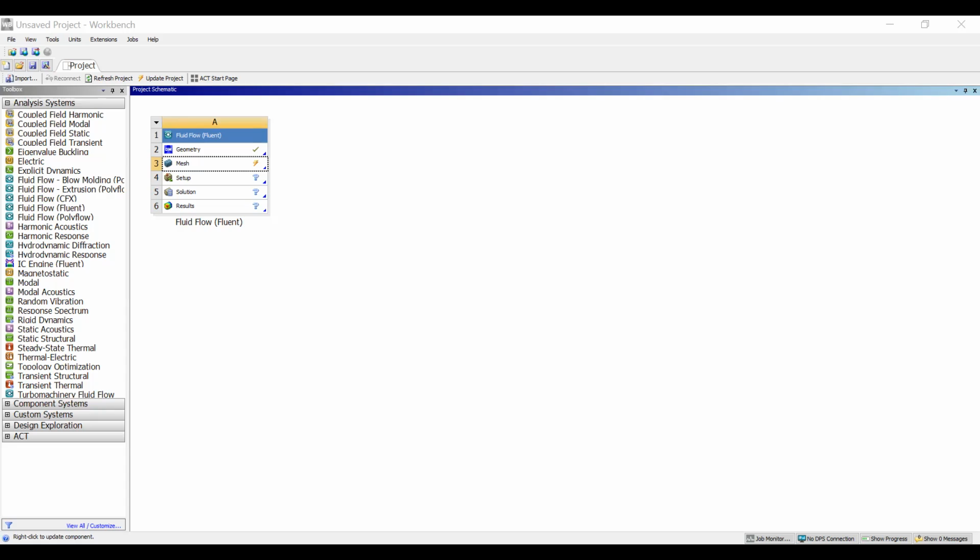And the last one we're going to do under our mesh, so we're going to right click on that again, insert inflation. And so for our inflation, our geometry again, and we're going to be doing the face this time. This was where I was getting ahead of myself because I clicked the face, the edge sizing, but that's actually what we want here. So we want that geometry, but then our boundary, we need to select the boundary, and that is going to be our edge in here. Edge and circle there. Apply that. Boom.